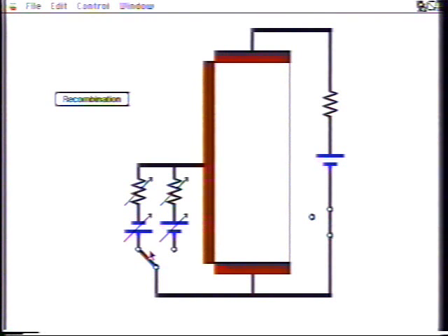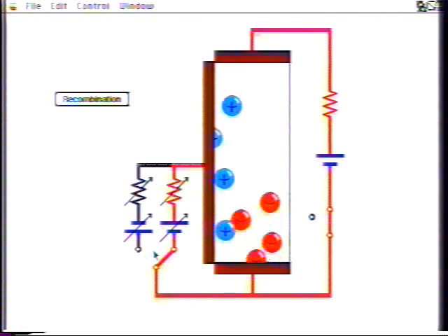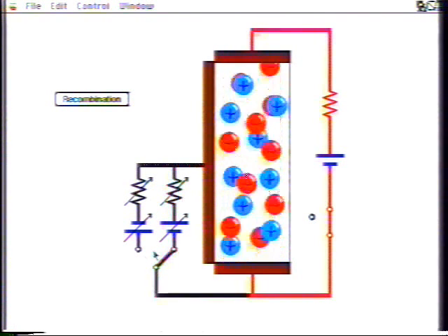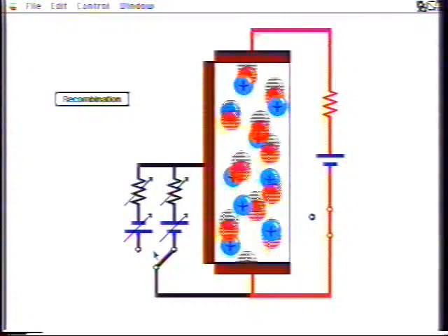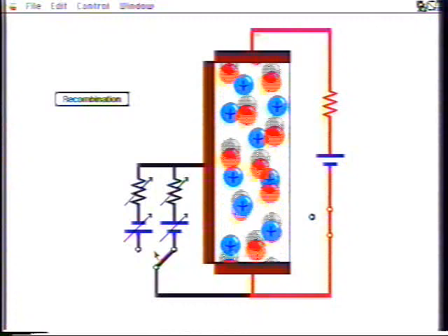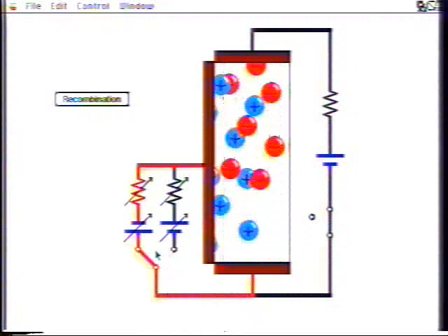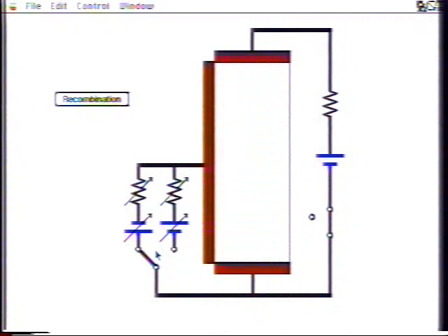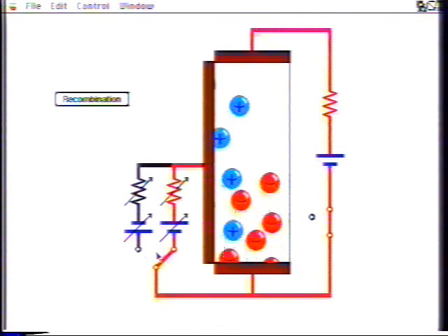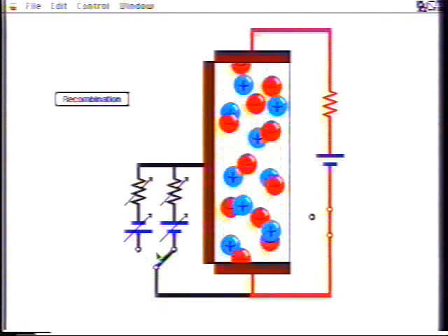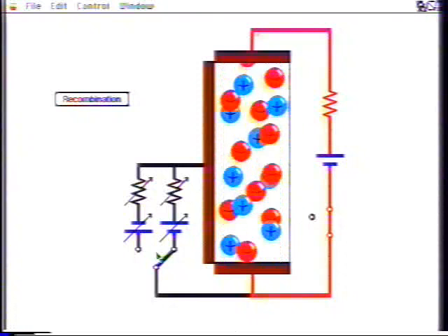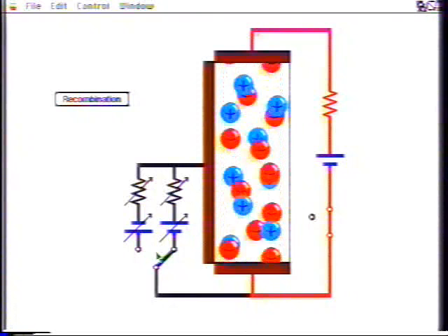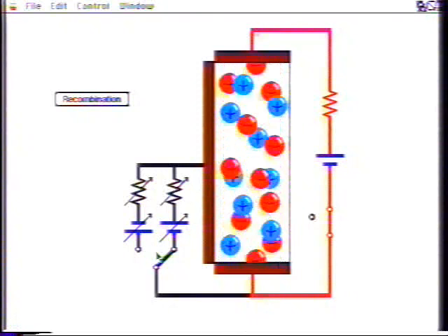There is, however, one significant difference between the BJT and the FET. In the FET, the positive controlling charge and the negative controlled charge are separated by the insulating layer that constitutes the dielectric of the gate capacitance. In the BJT, the positive controlling charge of holes and the negative controlled electron charge occupy the same physical volume, the active base region, which constitutes the base diffusion capacitance.